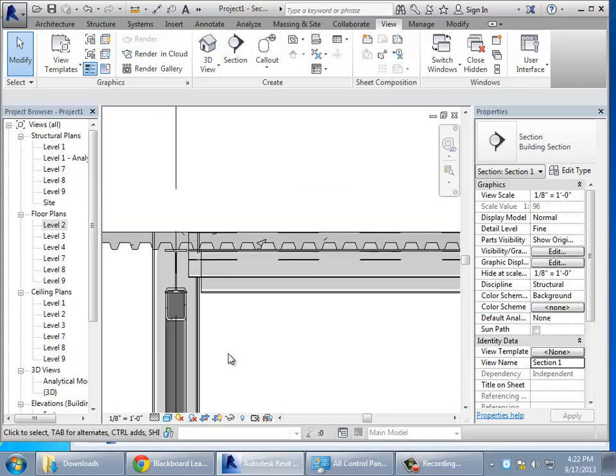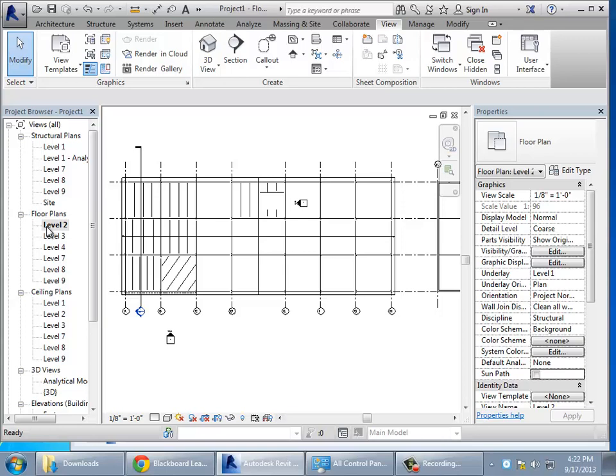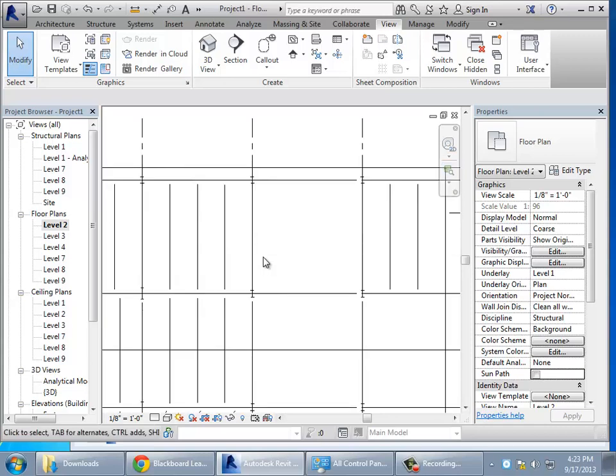The other thing that it's really good for doing is, if you go to those floor plan views, you're creating a building element model, so there's really an awful lot of information stashed in it. So you can look at this, like you often look at structural drafting. Great, all the lines are in place, but now I have to go back and add all the annotations. I have to go through and put in all that detailed information to do the drawing. But the truth is, since it is a building model, you can actually just pull the information out of the database and actually display that.